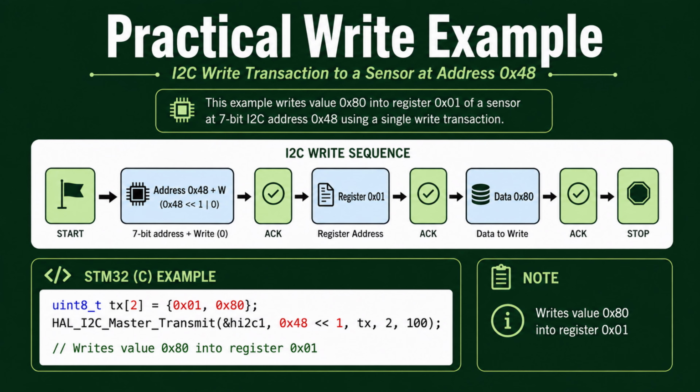In a real application, always check the returned HAL status so that address NACKs, bus timeouts, and communication errors can be detected instead of being ignored.